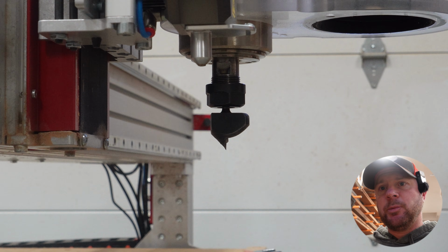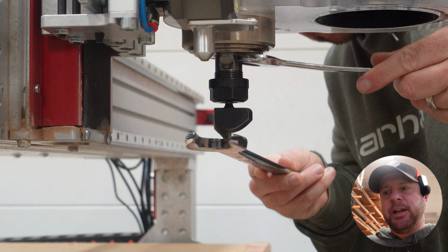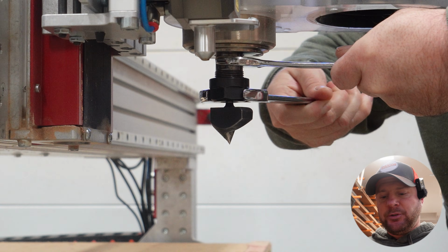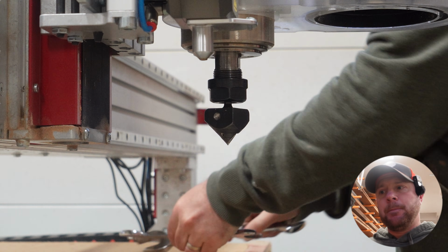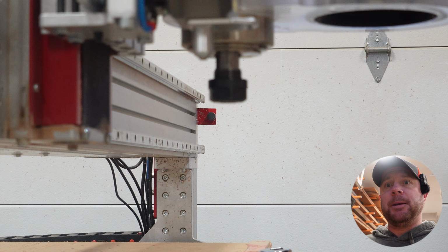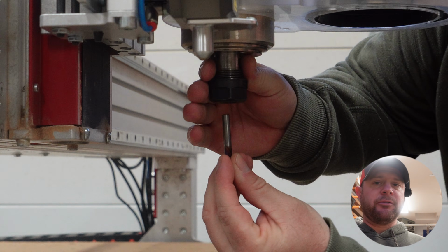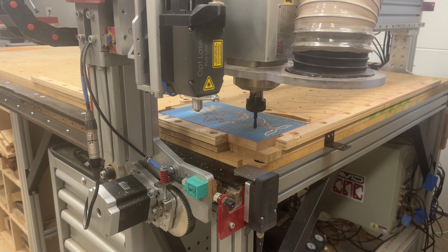Now that that V-carve toolpath is done, we need to change our bit so we can do the profile toolpath. And then we need to tell the machine that we've changed the bit, and that is because when you change the bit in the machine, the height of the bit changes. So the machine now needs to know where the tip of that new bit is so it can correctly predict where the surface of the workpiece is now based off the tip of that bit.